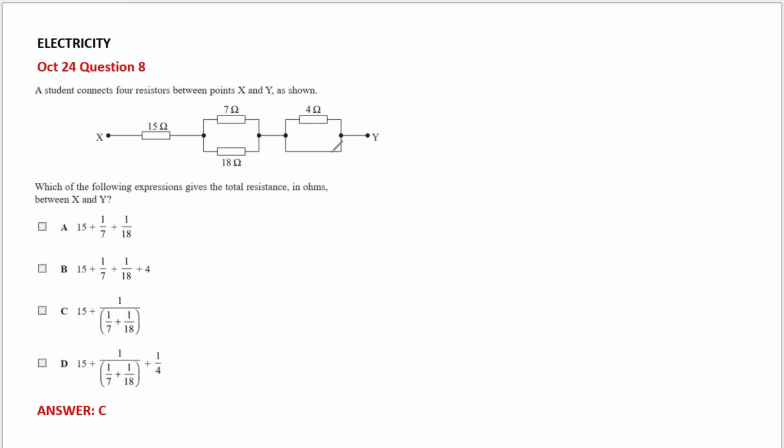It can flow in this direction without any resistance. And always remember, current chooses the path of least resistance. So this path has no resistance or negligible resistance compared to the 4 ohm path, right? So all the current will flow through this part and no current will flow through the 4 ohm resistor, meaning it's actually not part of the circuit.